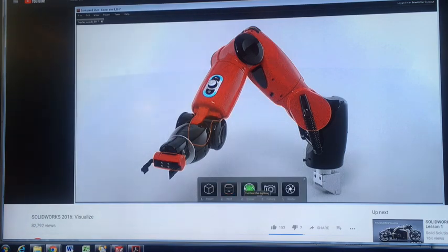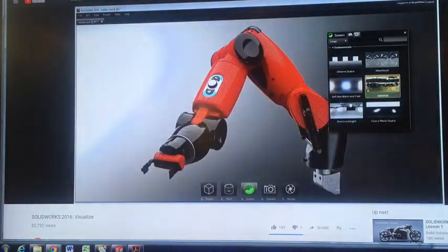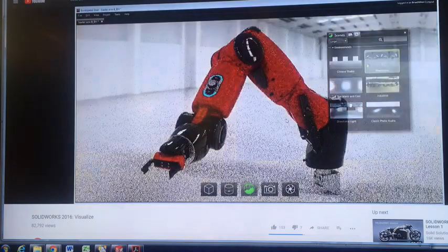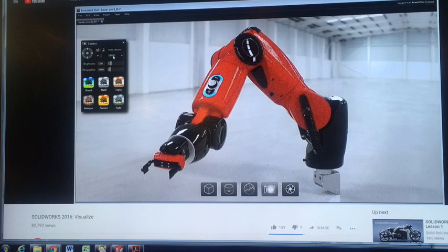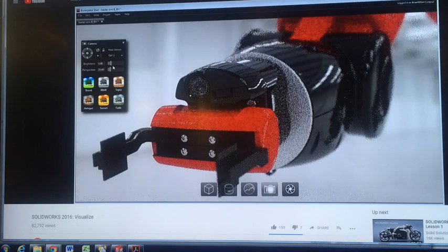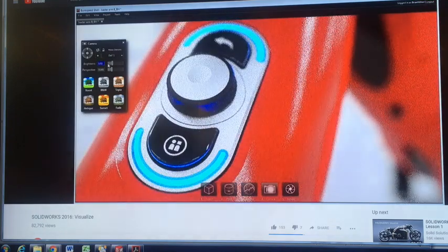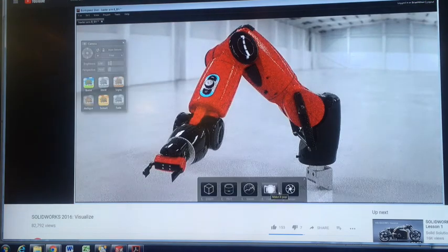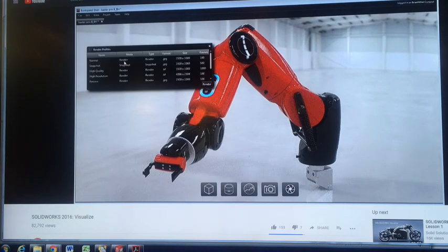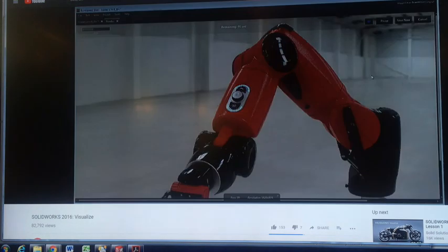Just like materials, environments are applied by dragging and dropping them into the viewport from the library. Environments can be dynamically positioned and adjusted to get the lighting, shadows, and reflections just right. Multiple cameras can be used in order to generate a variety of image styles. Depth of field, artistic filters, and other camera effects help to deliver truly photographic images. Final renders can be initiated using either default or pre-configured render profiles. Once started, the image progress, estimated time remaining, and pause option are conveniently displayed.